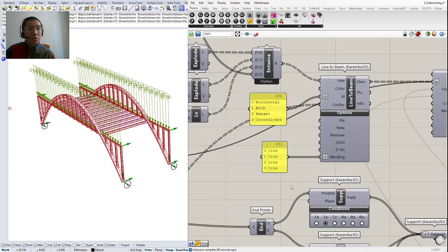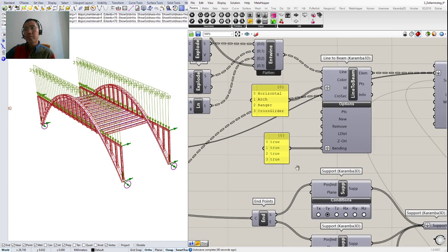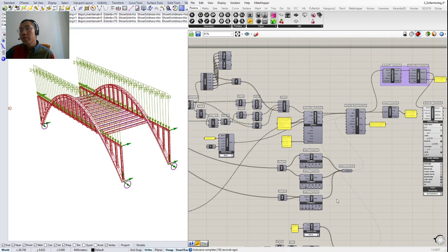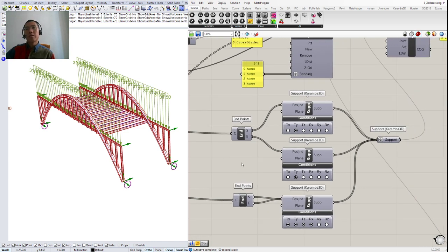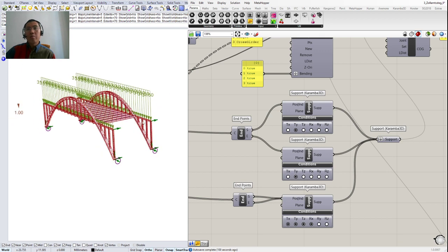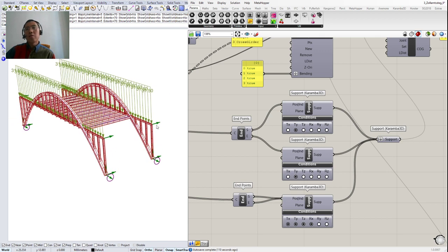There was a question in terms of the logic of setting degrees of freedom and supports and joints. I think in this example we haven't worked with joints, but you can look at the supports. When we are looking at the support conditions, we are able to support each point in a translation axis, X, Y, and Z, or on a rotational axis, so we can fix them. By checking this tick box, you can activate that this support position is locked in this axis.